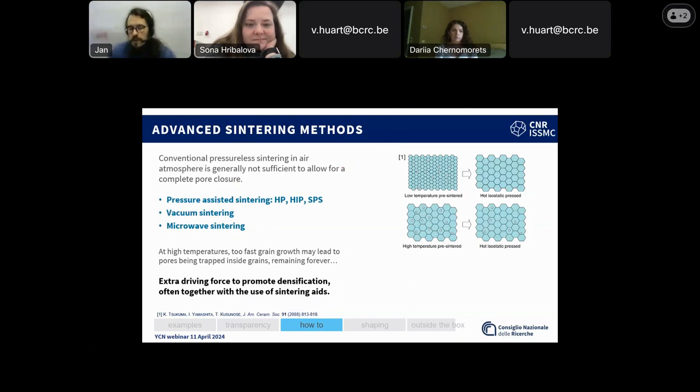Well, alumina has been produced very dense many times by different researchers, by different producers, and usually it's not transparent, even though the density is very high, because you might have relatively big grains and it is material that's optically anisotropic. What you can do is you can reduce the grain size. If you reduce it significantly, then you start to get some transparency.